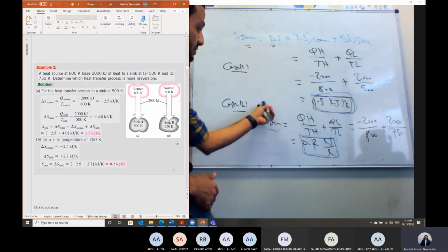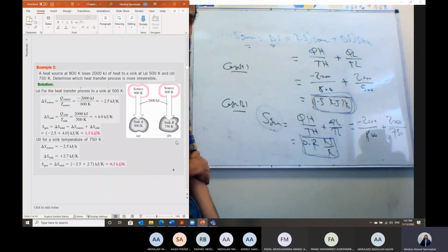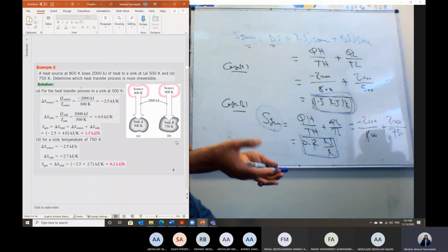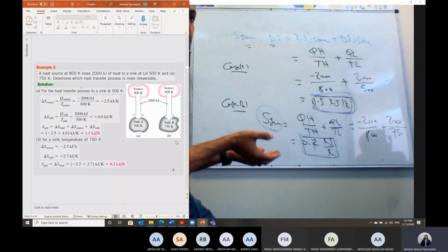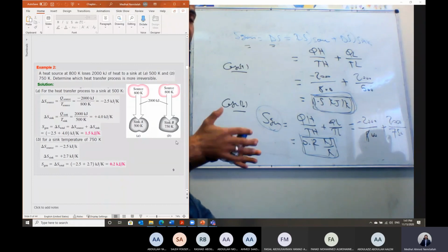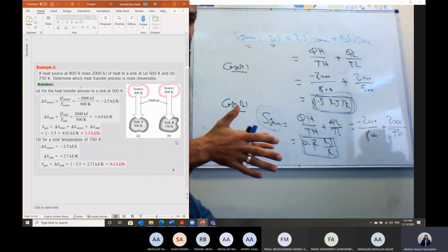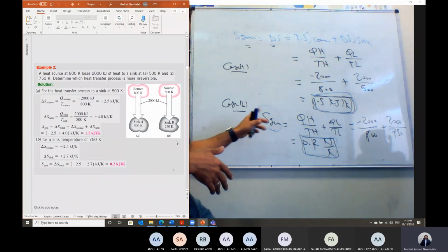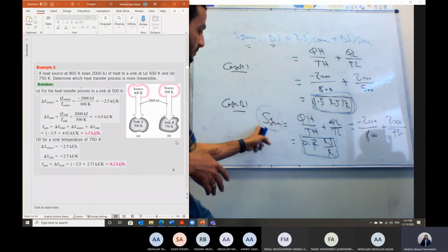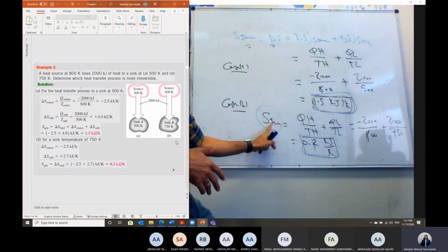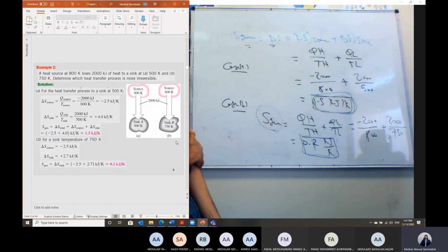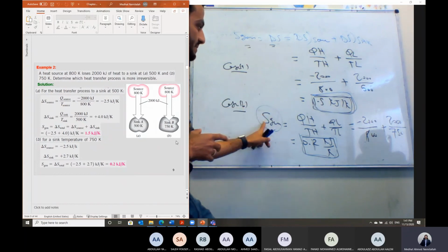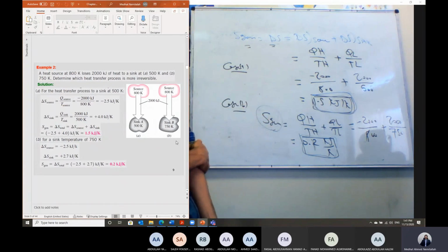So we have the entropy generation, which is the entropy created within the system due to the kinetic motion of the molecules, due to the irreversibilities within the system. Because all of the irreversibilities will be converted into heat. This heat will be taken by the molecules and it will be dissipated in the kinetic motion of the molecules. We cannot convert this heat into work. And that's why when you calculate the entropy generated within the system, this is a direct reflection of the losses within this system. Any losses just appear in the system in terms of entropy generation.